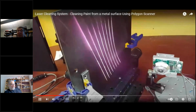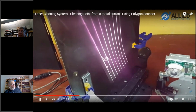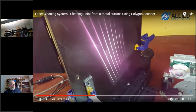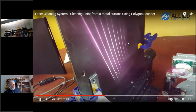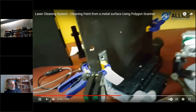So this is actually a prototype polygon scanner. This is not the one that we are using in the laser system. This is an inexpensive polygon scanner, and you can see that the different facets are not aligned. That's why you see there are 8 lines in here. So these are not happening simultaneously, but because they're so fast the camera could not distinguish that this is happening one at a time.